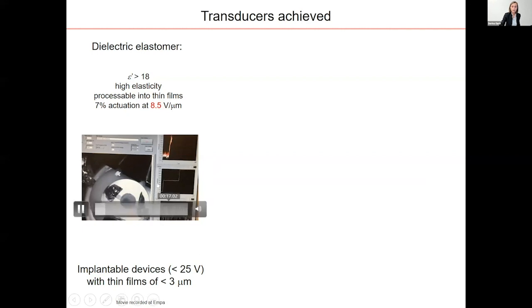And what you can see here is an actuator. We apply a step of 100 volt, which you can see here. And here you can see the lateral actuation strain, and you can also follow this dot. So you can see that at 1000 volt per micrometer, which was the maximum voltage which we applied here, we have huge actuation.